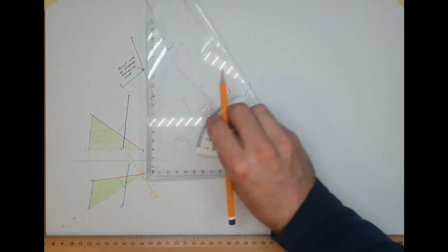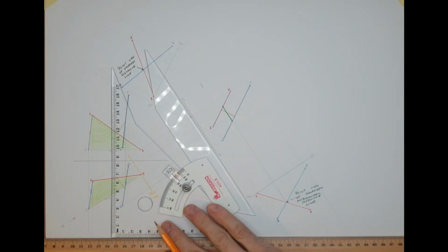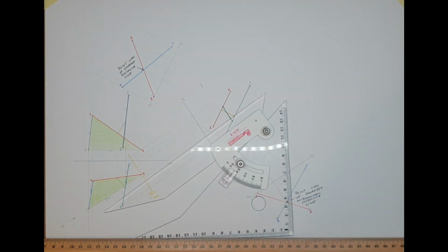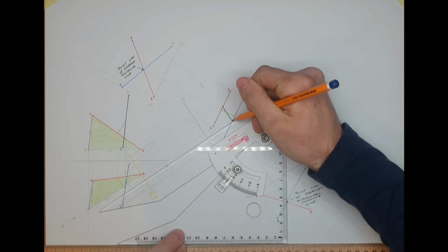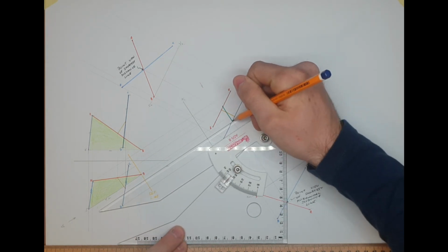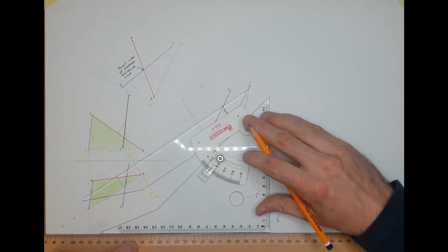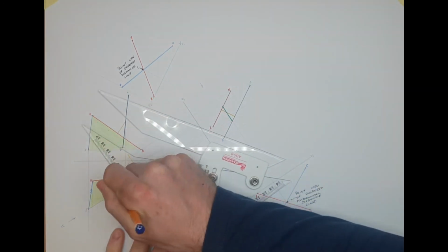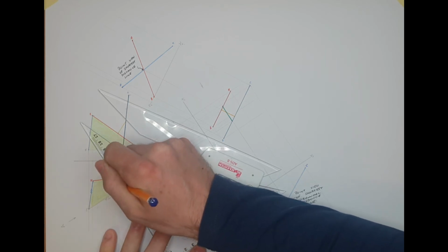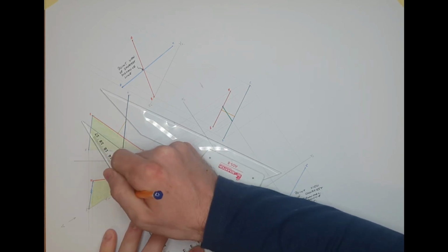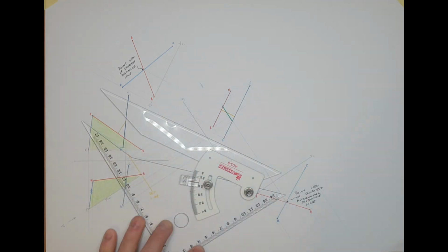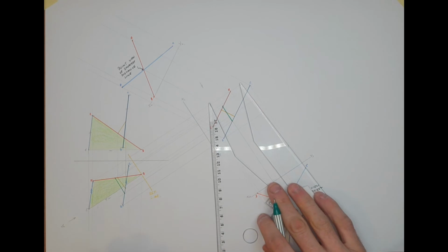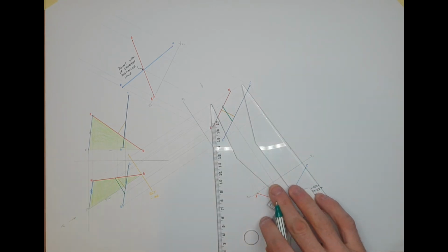I think this time, because I've set up my adjustable in line to look along with the XY line, X1, Y1 line direction, I think it should already be set to the correct angle for projecting down to plan. Well, the end of the green line is right there. And the end of the green line is right there. And the red. And where is it? It's there. There we go. That's our shortest horizontal distance. Right there. Little bit of a change there from the yellow line.